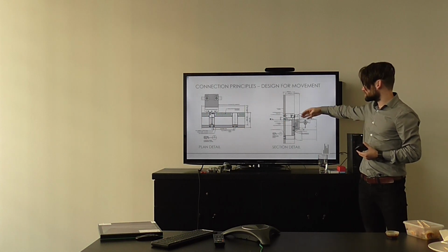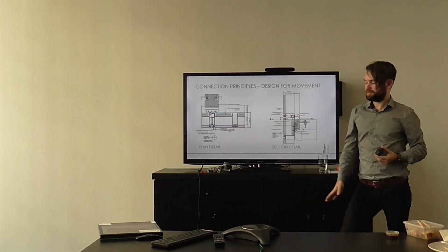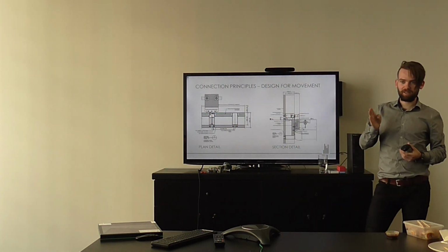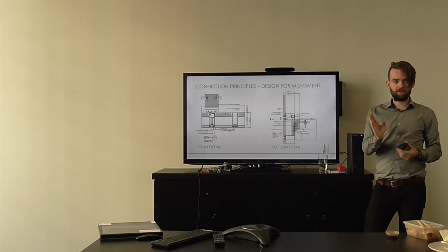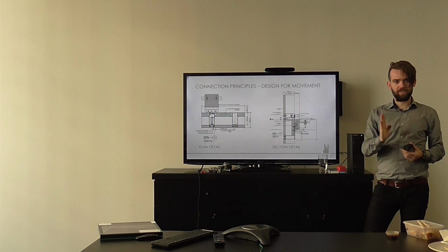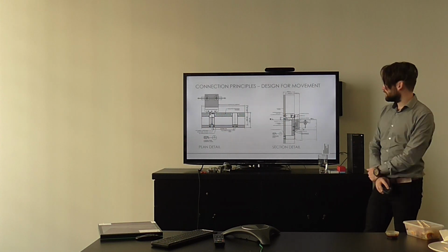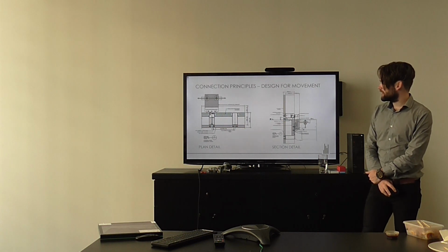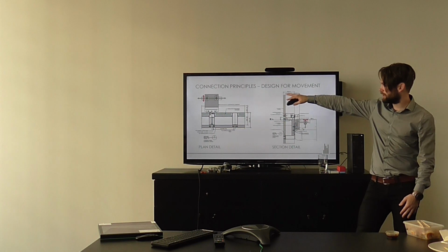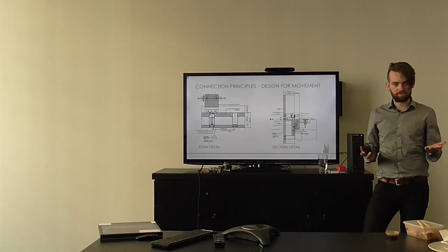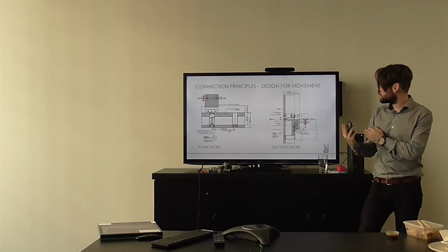And then we also have the situation where this bracket fixed off the back of our mullion needs to be exactly where our mullion is, and our mullion needs to be exactly where it needs to be. So just in case something's slightly off, there needs to be some play to move things to each side. So probably the first thing we do when we plonk our panel on is make sure we get it roughly in the right direction in a lateral sense. We can do this with our halving channel, which we have at the back there, which has been shown for the purpose of allowing us that large tolerance.